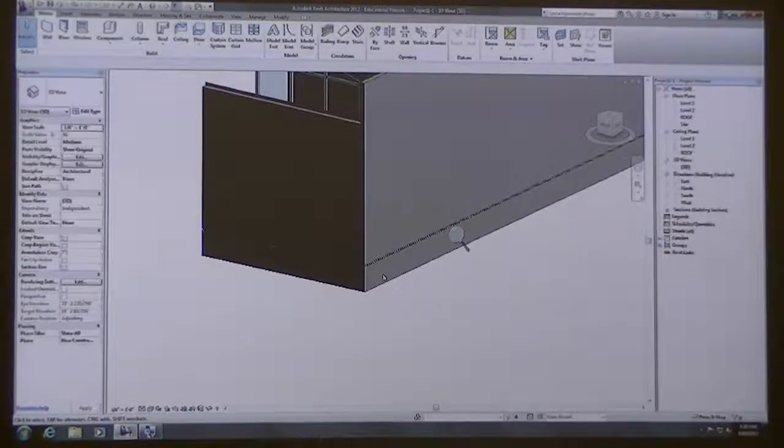So you can add as many reveals as you want. You could keep adding more and change, just like the spreadsheet when you build a railing system. We kept inserting more rails and then applying that particular profile shape is going to be 3 foot from the base, or then 6 inches from the base, and we gave it all these different heights. You can do the same thing with the actual reveals.